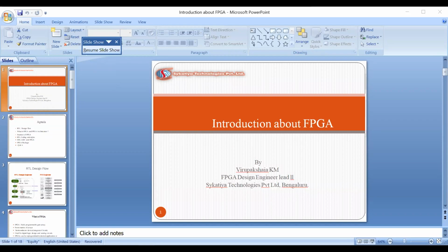If you are using only an FPGA, you need an external processor. If you want to do processing operations with the FPGA, you have to purchase an extra processor. So you can go for the SOC, and you will get both the ARM processor as well as the Altera FPGA. I am just giving the Altera SOC here. It may be Xilinx SOCs or Microsemi or anything. Altera SOCs are used more widely than Xilinx. As I told, it has an ARM processor, but it may be any processor, not only ARM.